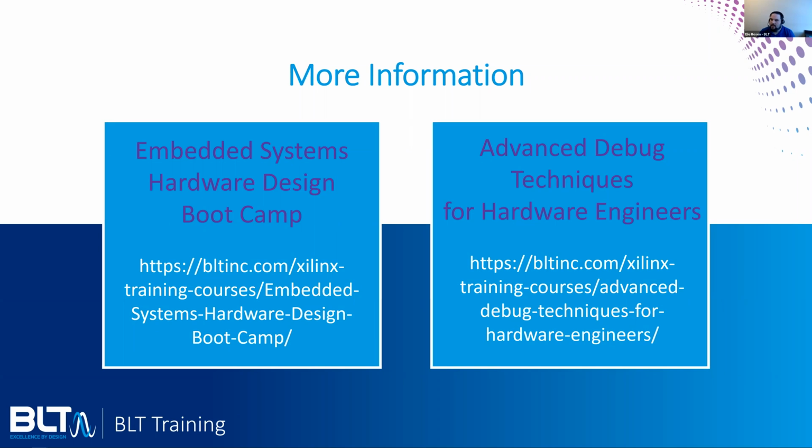Another question that we have is, does the cross-triggering work in the same way with the SDK? And yes, it does work in exactly the same way. Where that cross-triggering icon is a little bit different, but the premise is still the same. Also for the Zynq 7000 series, the ports aren't named exactly the same as they are in the A53, and information on that could be found in the Zynq 7000 technical reference manual.